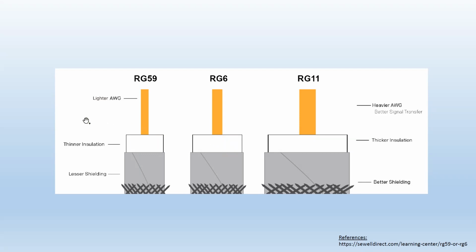There's one more cable that I didn't put on here, the RG58 as opposed to 59, and it does have a different characteristic impedance than these three. I can let you in on a secret: all three of them have a characteristic impedance of 75 ohms, and RG58, not 59, has a characteristic impedance of 50 ohms, right?